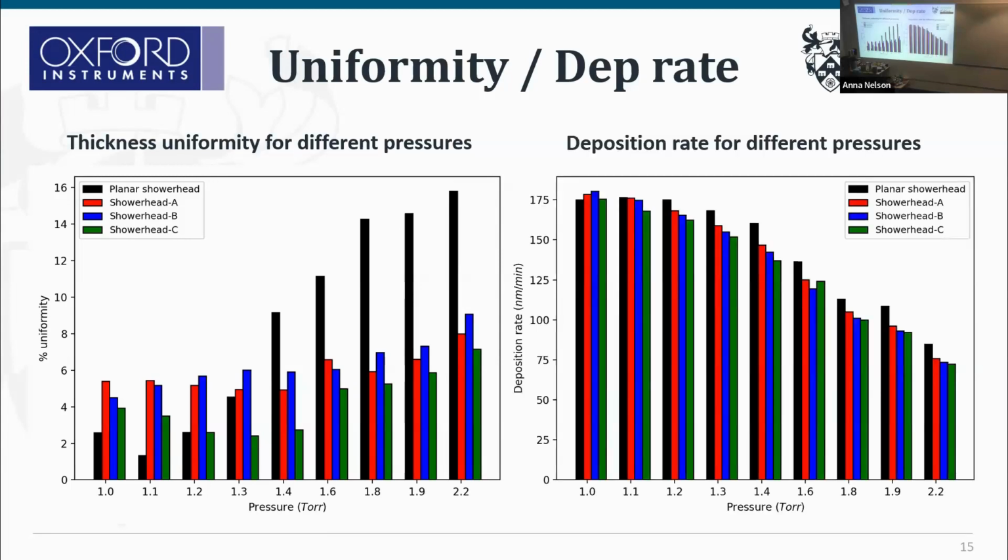So here we are not improving the uniformity at the cost of the deposition rate. If we compare the structured and planar shower head for these cases, we can see that the deposition rates are almost the same for a particular case as compared to the planar shower head.